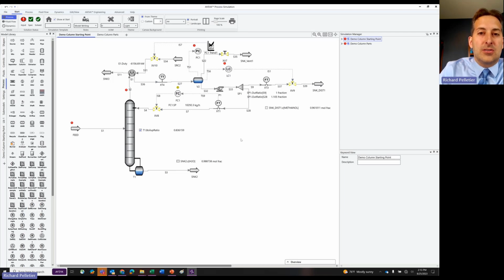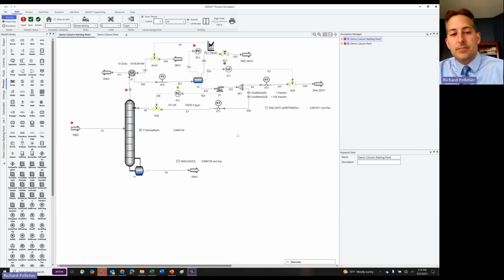The whole reason why we externalize condensers and reboilers is because every condenser and reboiler is different and has different ways of being configured. So this is a pretty straightforward standard way of simulating a condenser build out, but this is not always going to be the same for every single column. So just want to make sure that that was clear.